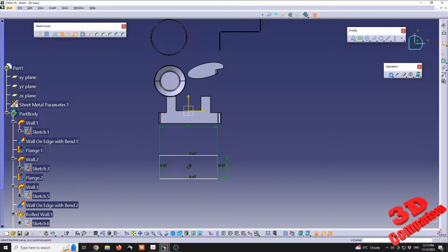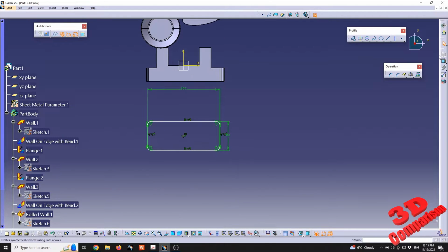So I'm going to click on corner, and I'm going to do a rectangle selection to grab all those 4 points. And now if I press tab, I will jump at the top on sketch tools and I will add 10 millimeters for the radius. So this is the initial hopper profile.